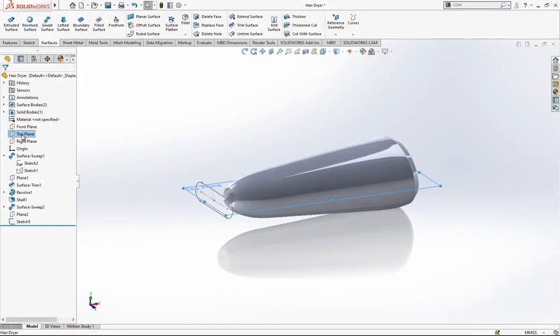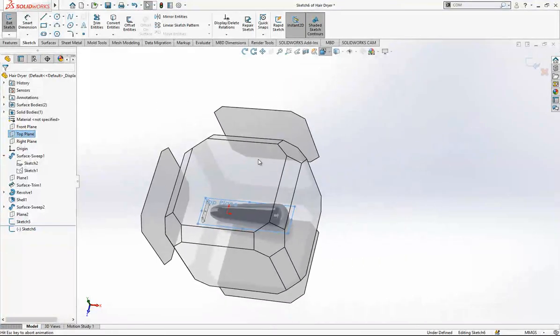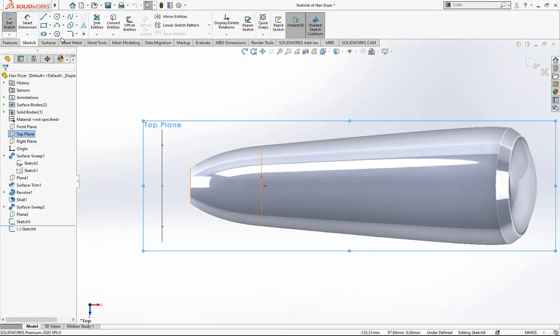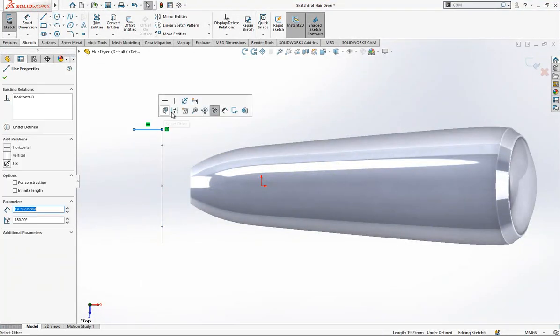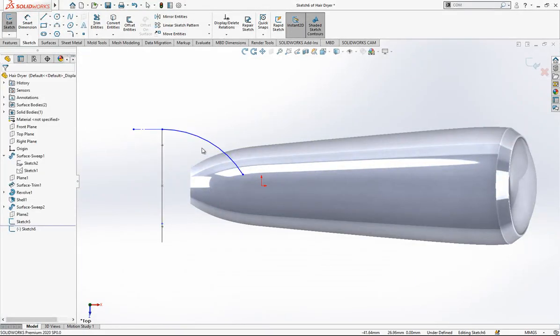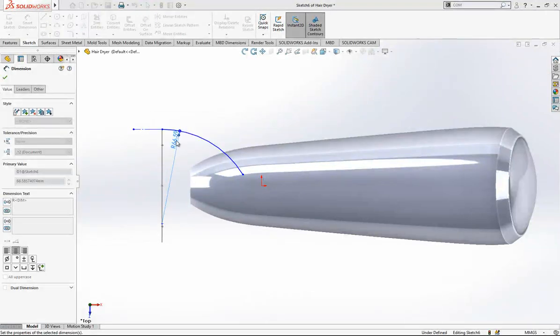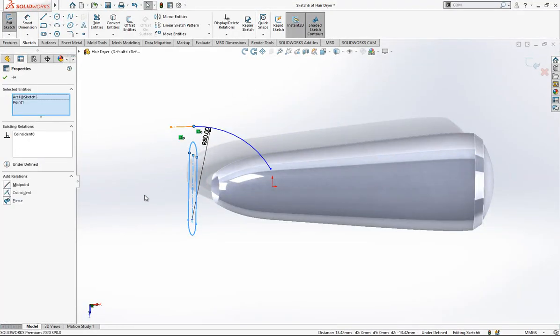Firstly, we are going to look from top plane, and we will create an arc there. We place a line here, arc here, radius 80, and in mode we just need to change our perspective, and we click on the object while Control is pressed, and we say pierce.